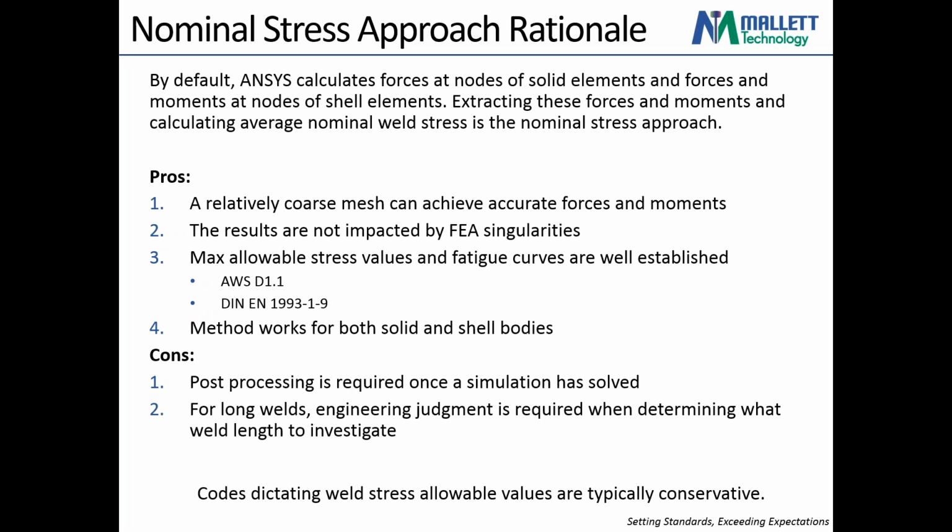Second pro, the results of the forces and moments are not impacted by FEA singularities, right? Generally, we see stress singularities because you have a force or a load applied to, let's say, a zero area, so you essentially get zero in the denominator. As you refine the mesh, stress goes to infinity. Or you have a right angle or a number of other cases. Because we're looking just at forces and moments and not stress, that's independent of the area calculation. So the weld stress results are going to be independent of the singularities.